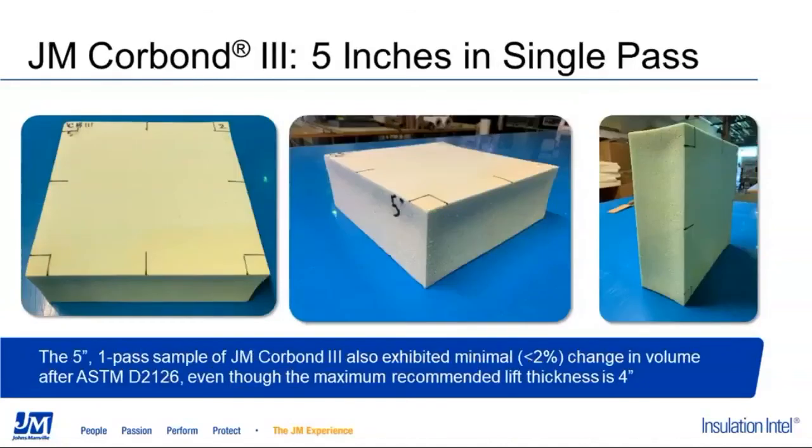We also wanted to see what Corbond III would look like tested this way when sprayed even beyond our recommended thickness to ensure we are leaving a margin of error. At 5 inches, the sample still exhibited the same excellent dimensional stability and lack of distortion. JM still recommends a maximum pass thickness of 4 inches, as ASTM D2126 does not cover all installation conditions.